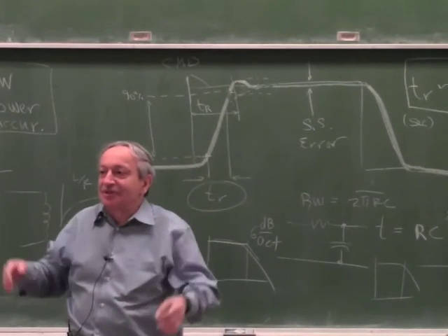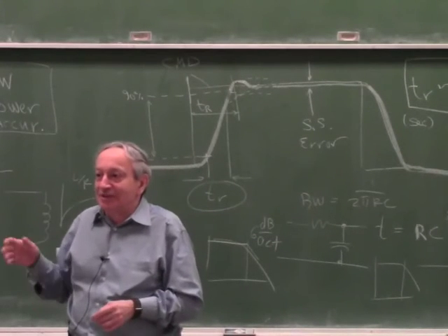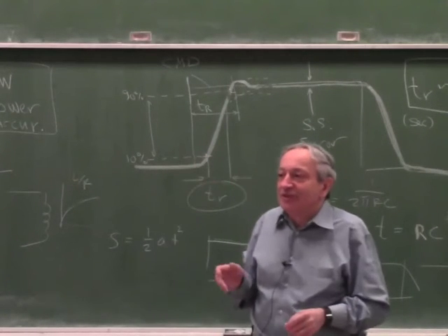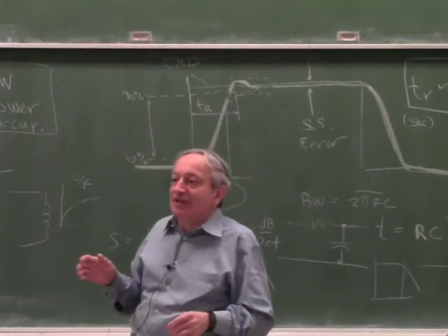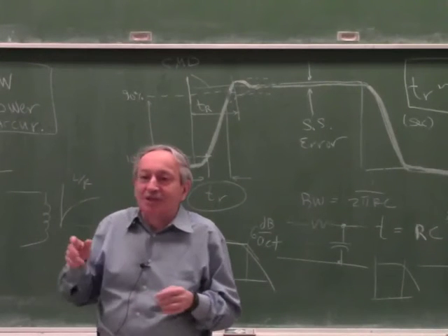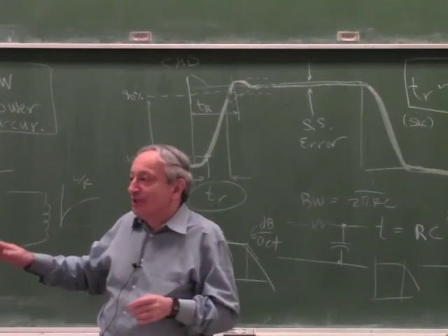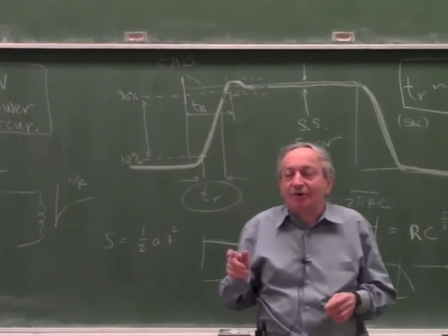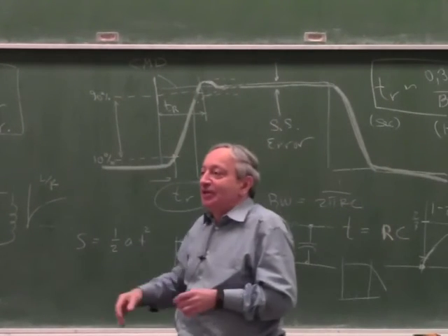And I don't want to start this whole lecture again on what aliasing is. But okay? But there is a second reason too. So if it's a digital system, it has to have a filter. Otherwise, some frequencies will get created which didn't exist. And these frequencies can be very low frequencies that the actuator will respond to. That's called aliasing. But there is a second reason why you can't just allow unrestricted bandwidths to get into the amplifier.